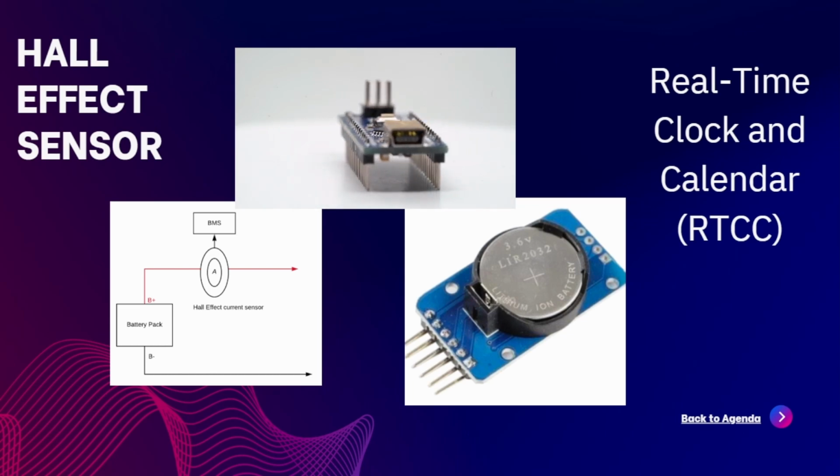Mainly Hall effect sensors are characterized by the following. The current reported by a Hall effect sensor remains accurate over time and temperature. Next, Hall effect sensors are isolated from the pack current, that means the battery pack current. Therefore, no isolation is needed. Also, Hall effect sensors suffer from offset at zero current, which changes with the temperature. So even if they are zeroed at room temperature, they will report a small current when there is none, as they get hot or cold. Frequent calibration is required in applications that have periods of zero current, such as an HEV.